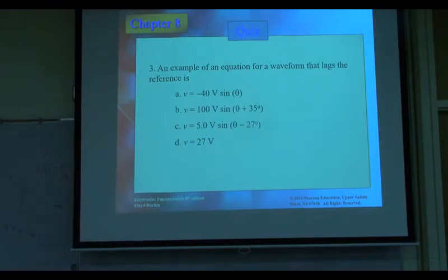For example, if you want to make a charger, it can only use DC. So you want to use this wall outlet to charge something like a radio. You need to rectify this AC voltage into a DC voltage. But this one is too high because this equals 120. If you directly rectify this one, the output voltage will be more than 170 something. It will destroy your device.